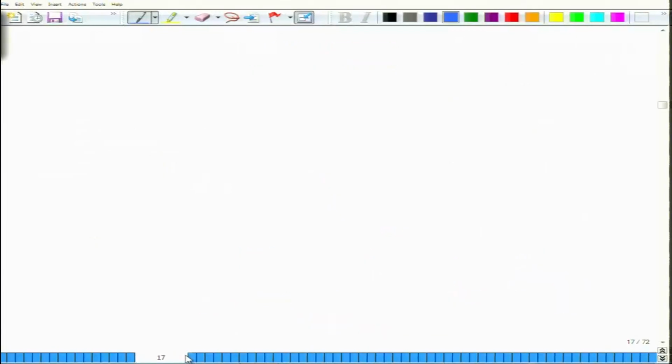Now instead of a coupler, we might elect to use what is called a circulator. A circulator is a very interesting device. It has 3 ports. We will talk more about all these devices; I am just giving you an overall idea of the different WDM components that we use. So this is port 1, port 2, port 3, and the working of this circulator depends on the direction of the arrow.